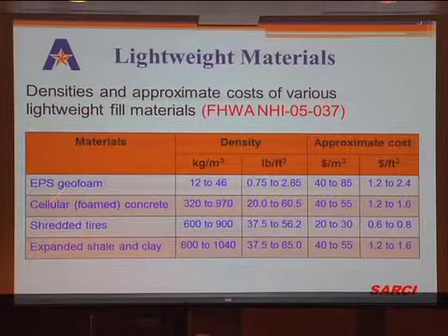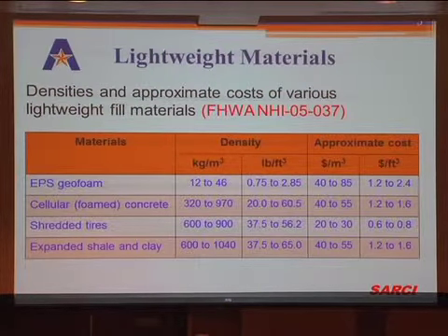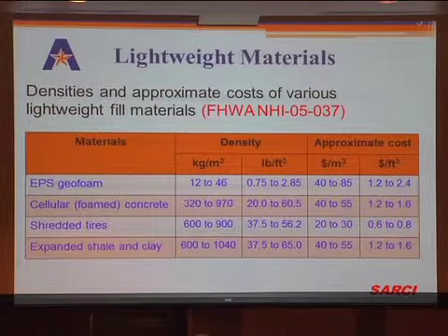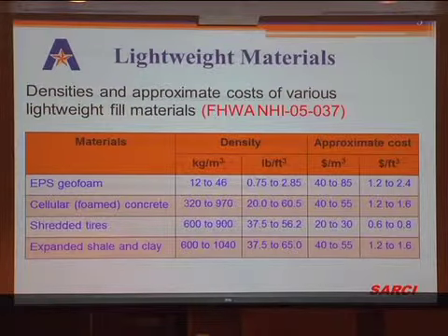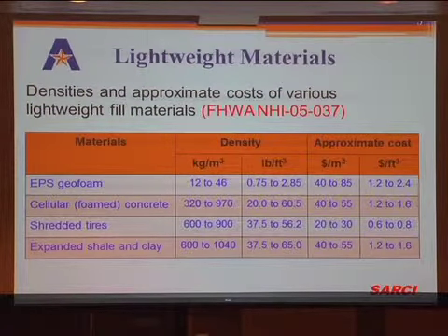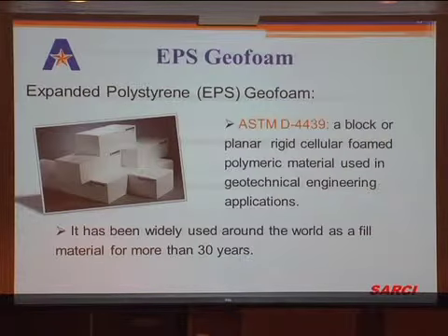So the one that we looked at is EPS Geofoam. You're talking about 40 to 85, around $50+ per cubic meter there. And again, they come in large blocks like this. So this is your foam material.